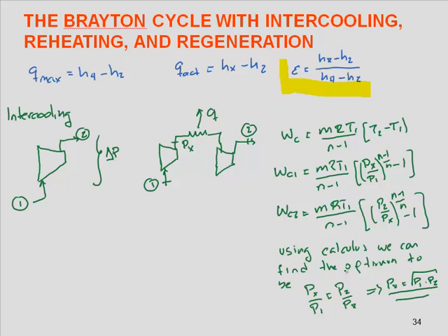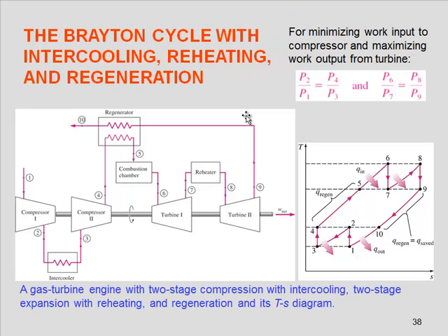So the effect of intercooling is shown here. What we are doing is compressing to an intermediate pressure, then we cool down, reducing its temperature, usually to the same temperature as at the beginning, and then compress again. This is the intercooling portion that we are seeing.